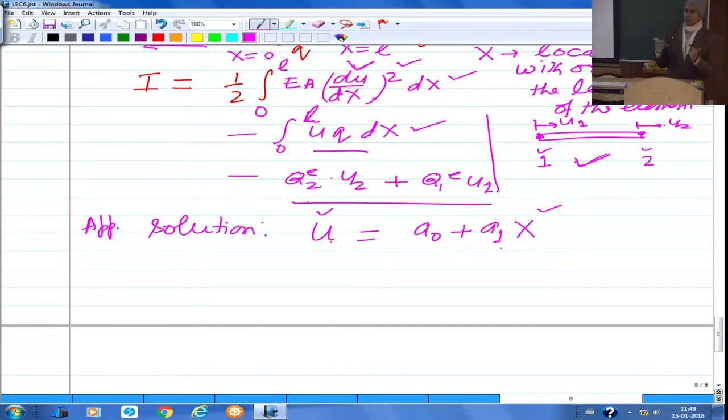When we look at the fourth order differential equation, Euler-Bernoulli beam bending, we will see that from the differentiability point of view, you need only a quadratic polynomial, 3 terms. But then the inter-element compatibility, that is continuity of primary variables across the elements, requires that at minimum you choose a cubic polynomial with 4 terms in it. That would be an example where the final form of the polynomial is governed by the inter-element compatibility.